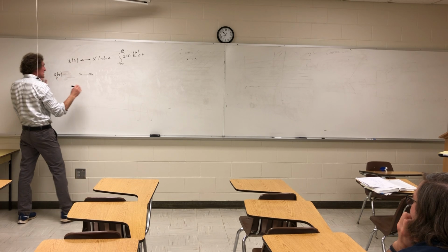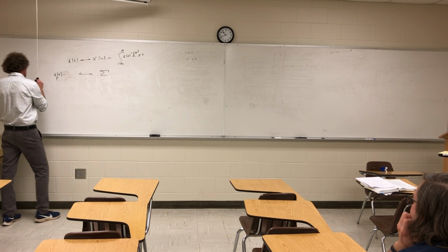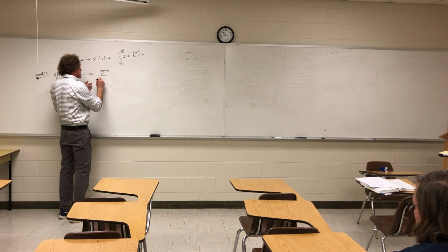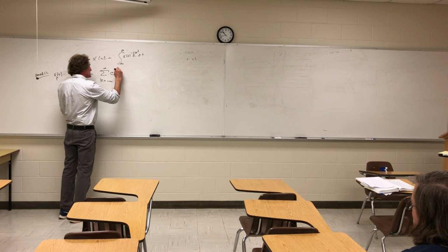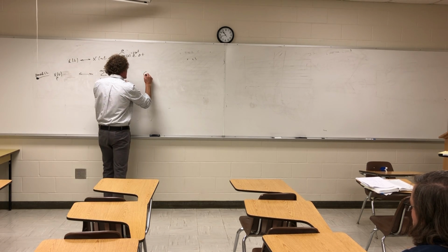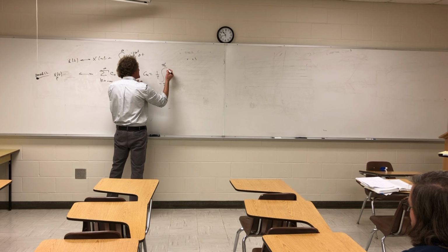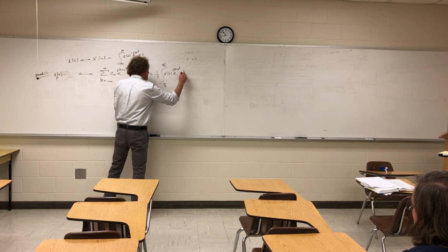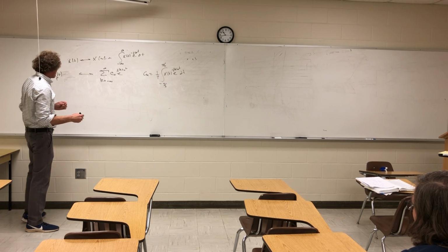and it's periodic, then what you end up getting as a Fourier series is going to be a periodic series here, where n goes from minus infinity to infinity, and I'll call it c of n times e to the j n omega naught t. And c of n can be found as 1 over T, the integral over a period from minus T over 2 to T over 2 of the signal x of t times e to the minus j n omega naught t dt. Y'all remember that, right? That's standard Fourier series analysis, correct, class? All right, usually we do a cosine series thing.